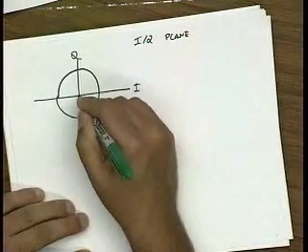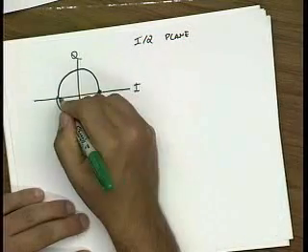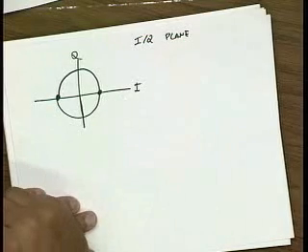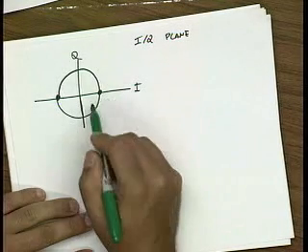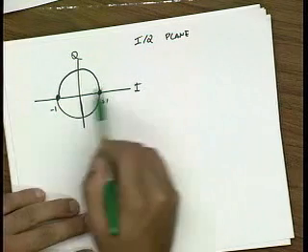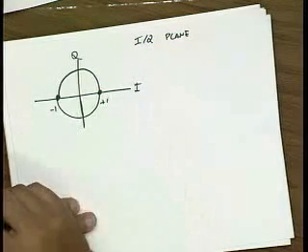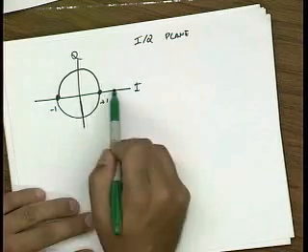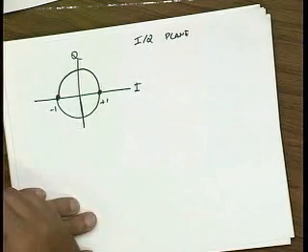So an example of that would be I could pick these 2 points and produce a digital modulation scheme where I either send I of, let's say, +1 or I of -1. And that corresponds to basically phase modulation. I'm changing the phase by 180 degrees.